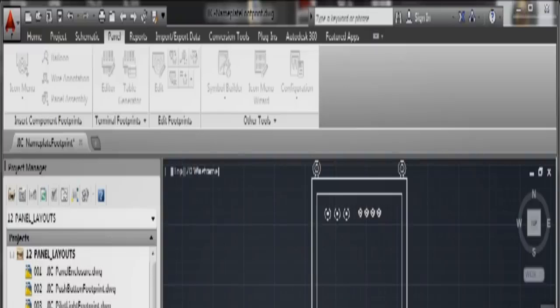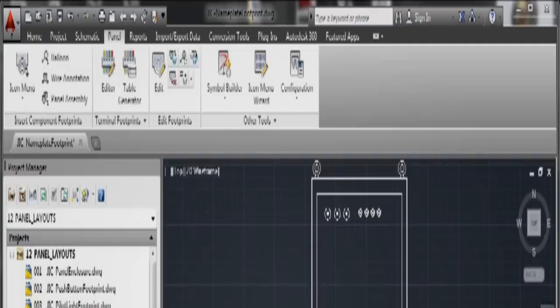And again, it's looking in the database for this information. So you'll notice there's a little green object here. A different footprint found. Do you want to change the footprint block? I can change it if I want to. I'm going to leave it as it is, like so. It searches for the wildcard match. And again, it takes a little bit of time to do this, so give it time to do it. You're looking in a big database for information.